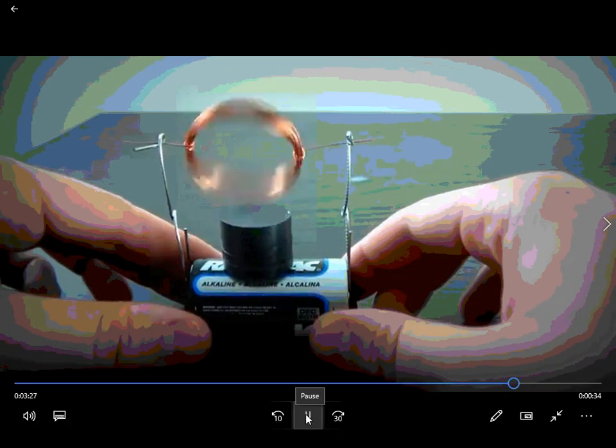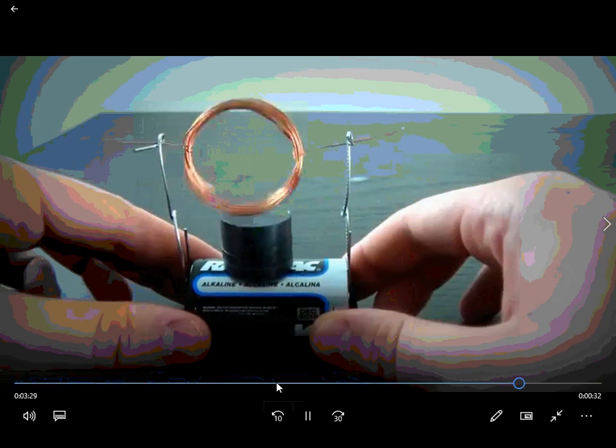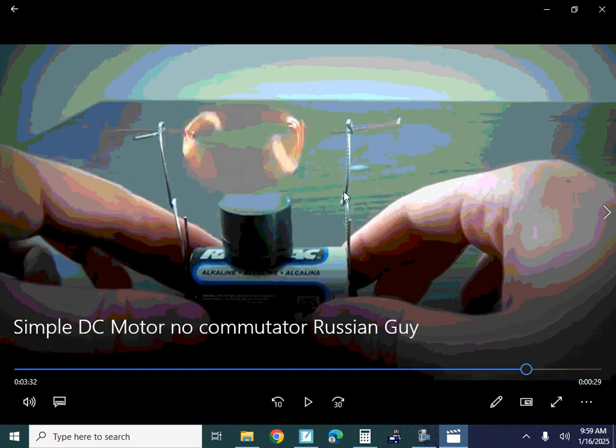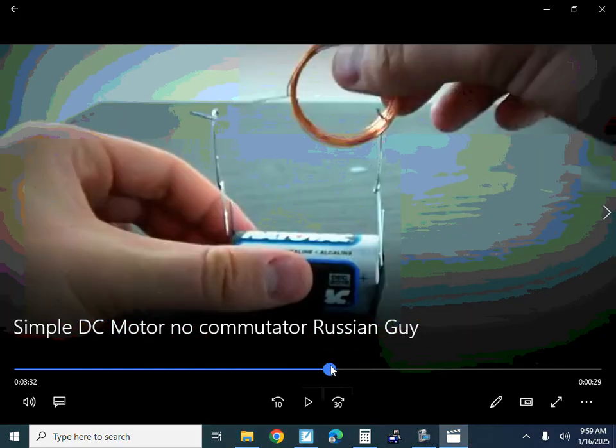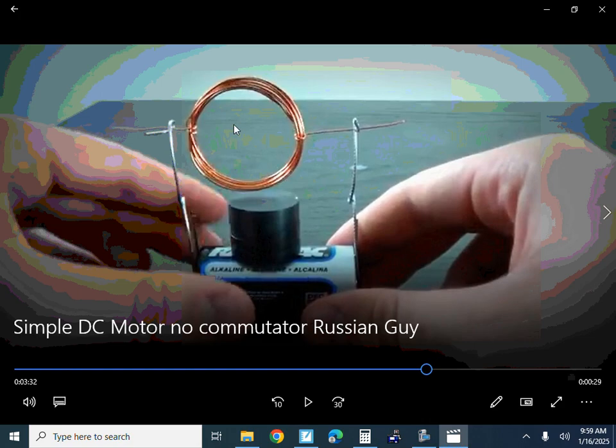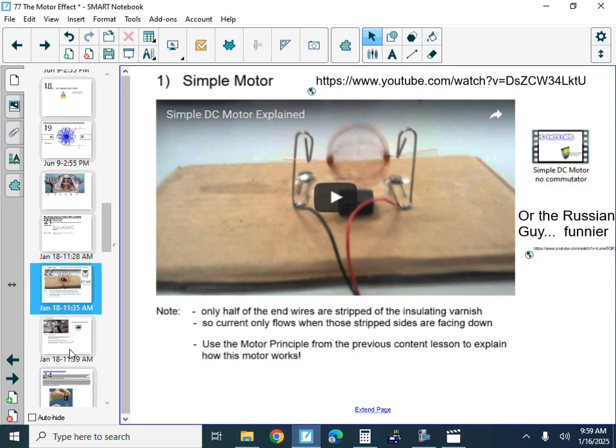This one is, though. I have a little working model of this that's definitely more finicky to make work, so wobbly and whatnot, but it's neat. So you could try to analyze it. Basically it'd be pretty easy if you picture the coil when it is, say, horizontal. It might have electrons flowing this way, and it would make a north. When it's horizontal, it might make a north facing the north here, which is going to cause repulsion, right? So if it's a bit on an angle and that's a north, it's going to cause it to rotate, and so on. Pretty easy to work through an analysis of that one.